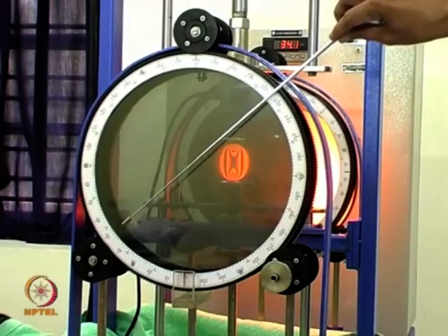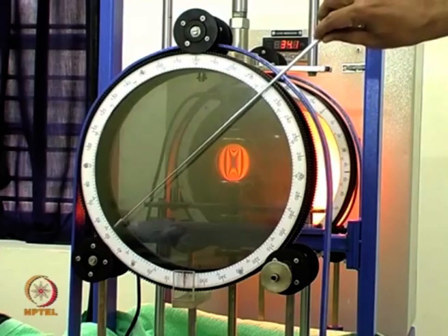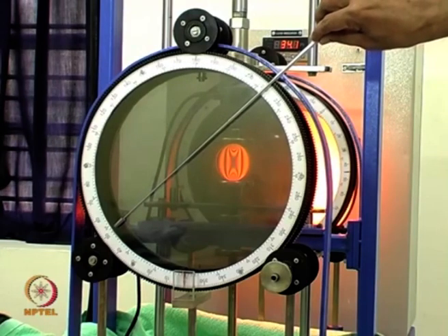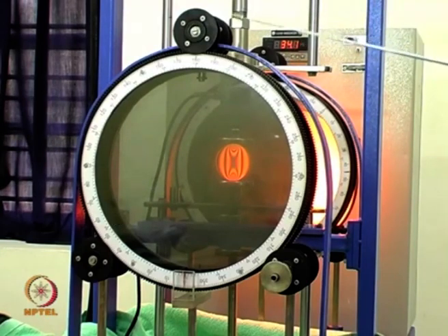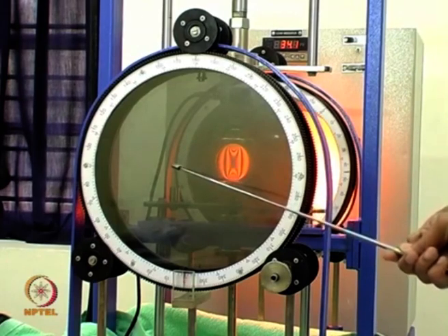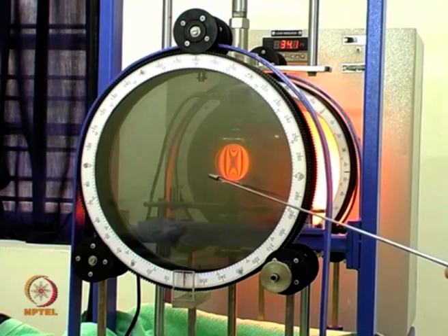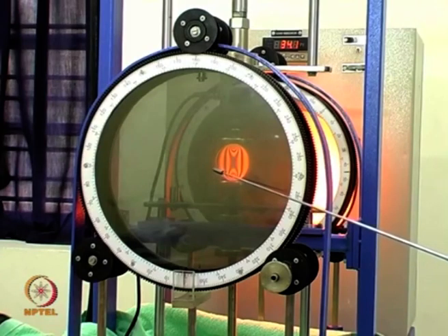The advantage of a sheet polarizer is you have a very large field of the order of 300 millimeters in dia, and they can be easily rotated by a simple mechanism. And what you see in the polariscope is the fringe patterns in dark field for a circular disc under diametral compression. The fringes have to be labeled as 0, 1, 2, 3, etc.